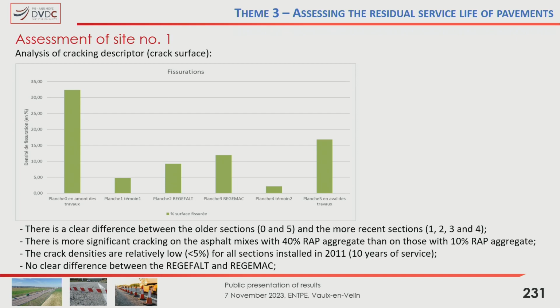The cracking densities, nevertheless, are relatively low. We were able to note that it was barely visible. This was the case for all the sections installed in 2011. So we were able to say that the surface still had another 10 years in it.